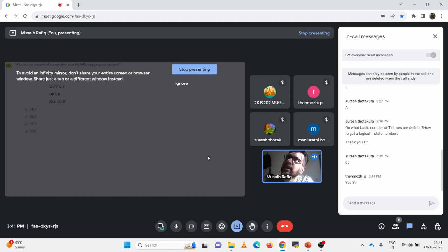So in the earlier slide, I said that the zero flag is one. I think I messed up there. The zero flag is one after an arithmetic operation when the result is zero. It is reset, Z equals zero, if the result is non-zero. So Z equals one if after the arithmetic operation the accumulator is zero, and Z equals zero if it's non-zero.